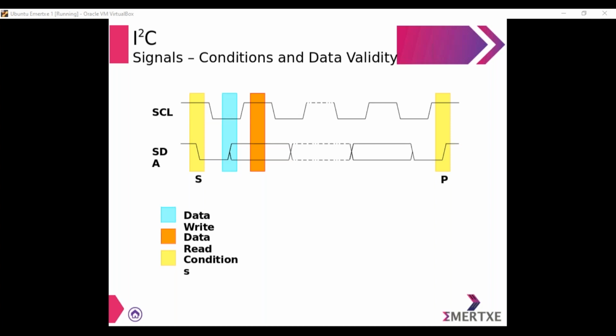So whichever has got the communication established will continue to communicate. All other devices in the network will not start or initiate the communication until they read a 1 from the data line. All other slaves in the network will actually be busy with their own task, or they might go to sleep mode to save some power.